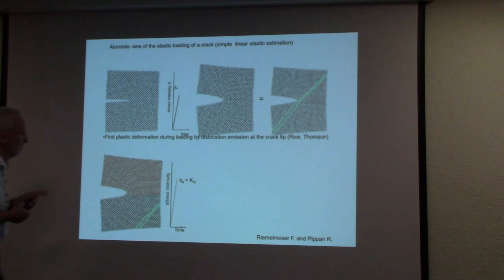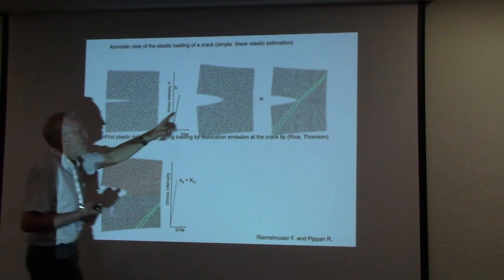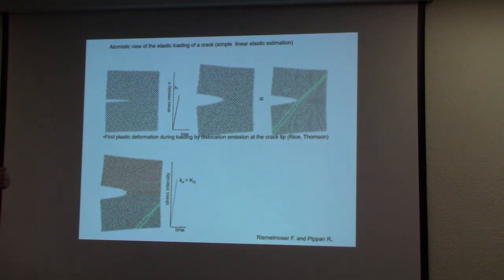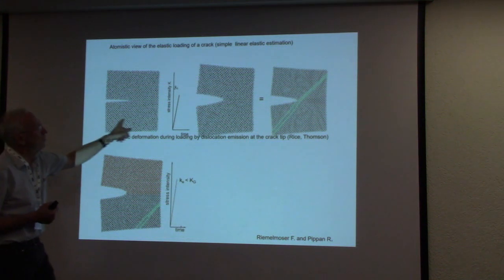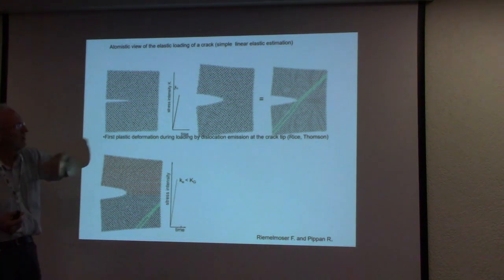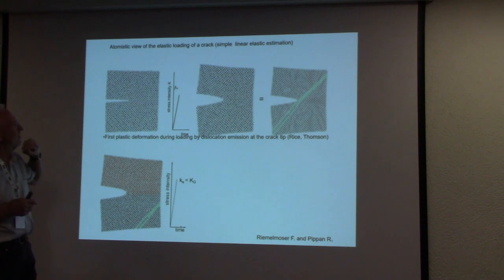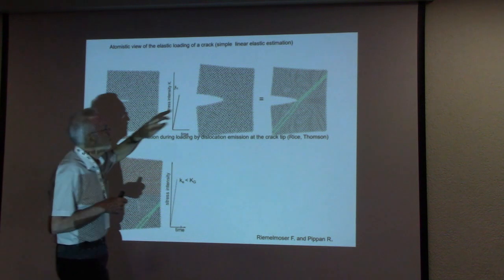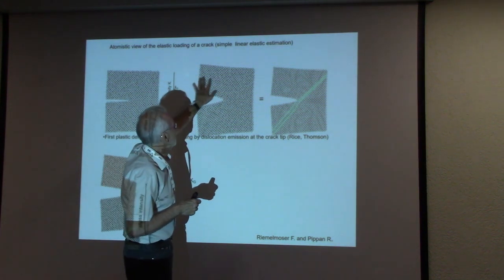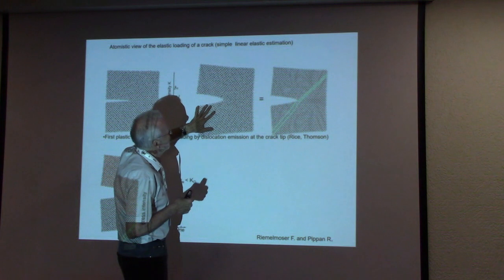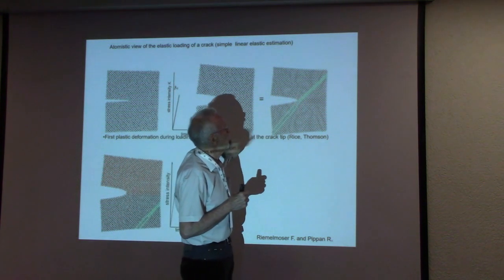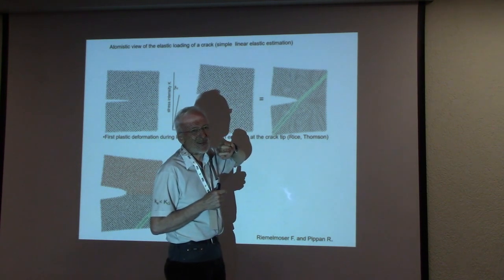What happens is that the crack tip itself generates dislocations. Here you see a purely, simply linear elastically loaded atomic arrangement. When you look carefully along this line, it looks like a really perfect crystal. But if you look here, this may be like an embryo of a dislocation.